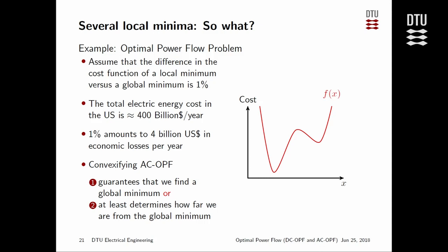Of course, convex relaxations are now under development. They also have their weaknesses, but the main motivation is to find a way to identify the global optimum of our original AC OPF problem, and to make sure that this is the optimum. So there are two reasons that we're looking at that. First is exactly because we really want to achieve that global optimum.